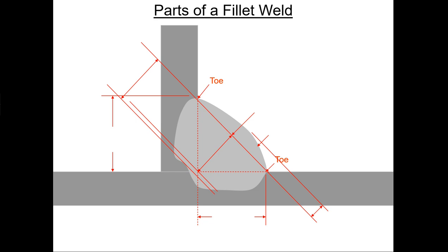Now, as a visual inspector of aluminum especially, you need to look at the toes of the weld. This is a common place to look to see how the heat flowed into the material, where the transition point comes. And these toes tell us so much about a weld, and especially about aluminum. This should never roll back, for example. I should never roll away from the edge like this, right? We should always see a smooth transition of material between the base and the weld metal.